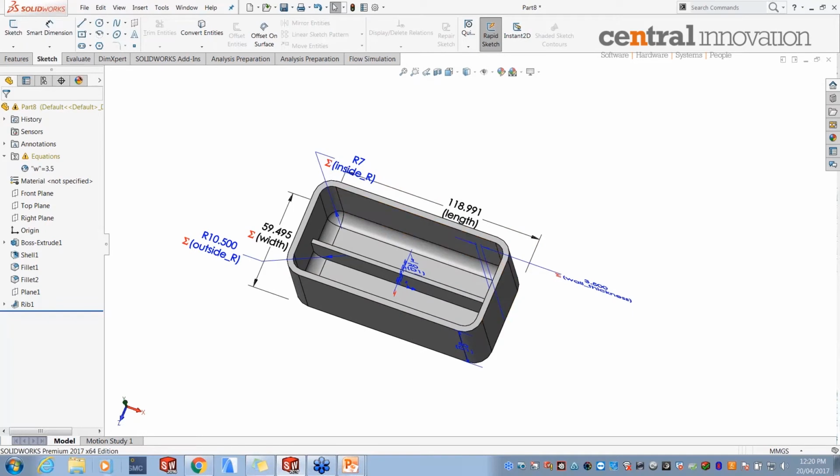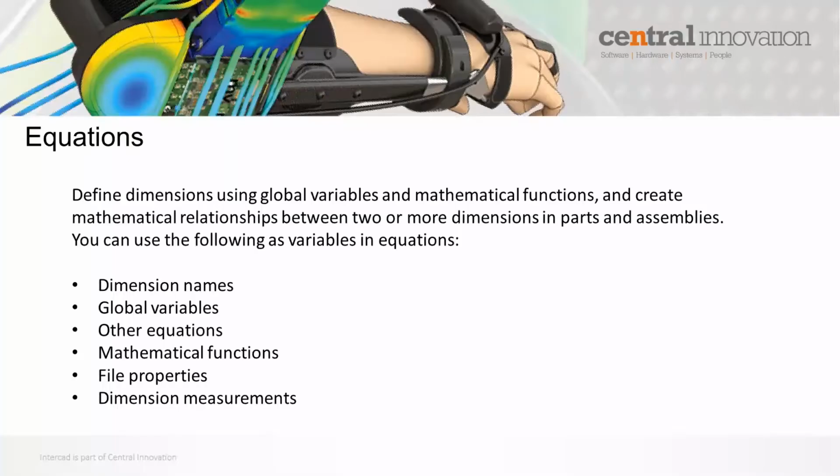And just to do a bit of recap, let's go back to my PowerPoint slide. Basically, the most important thing is it's always good to dimension your features and give them a proper, sensible name, and try to avoid having spaces in between or dashes. So use underscores instead. There's no harm in using spaces and dashes, but the problem is it gets a bit difficult when it comes to troubleshooting later on.